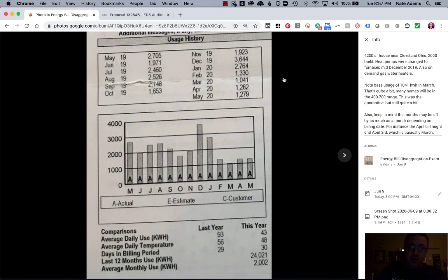And even though it was only 80 degrees the day before, the two systems had used 120 kilowatt hours between the two of them. It's like, holy cow, that's a crap ton. So we had to figure out what was going on. Turned out to be leaky returns that were pulling from the attic that was driving that up.